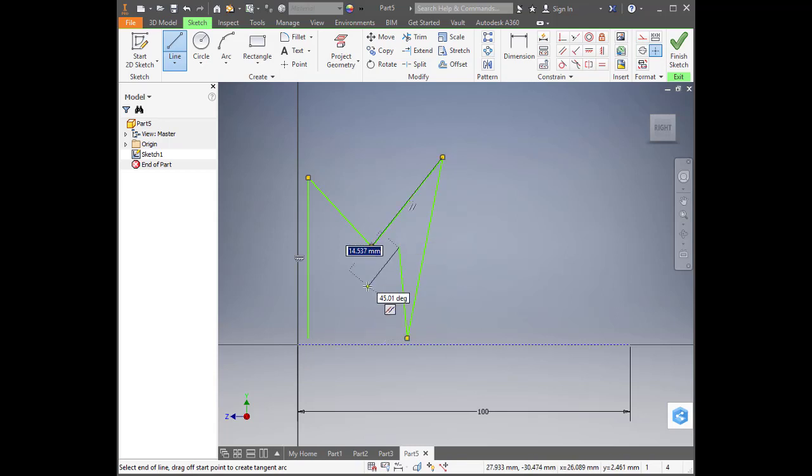We'll make it 3D. You'll notice little lines pop up as I draw. So for example, at the moment I've got one running up here. That shows that my dot is vertically below the other one. That's really useful as a guide when you're drawing. Okay, I'm going to click to position that. Now to stop drawing lines, I'm going to right click and cancel. Right, so there's my M shape. Let's have a look at that. Let's see if that's any good.